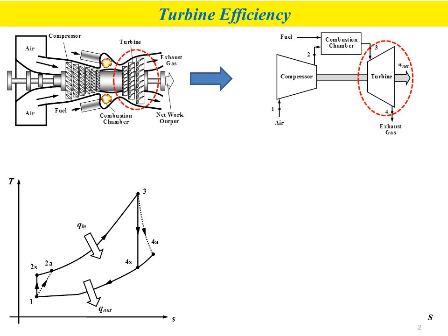Okay, in order to describe a process that we have learned in thermodynamics 2, we need to draw a TS diagram. This is the TS diagram for the Brayton cycle. We have the process for the compressor from state number 1 to state number 2, and also the expansion process in the turbine from state number 3 to state number 4. So there are two processes for each component.